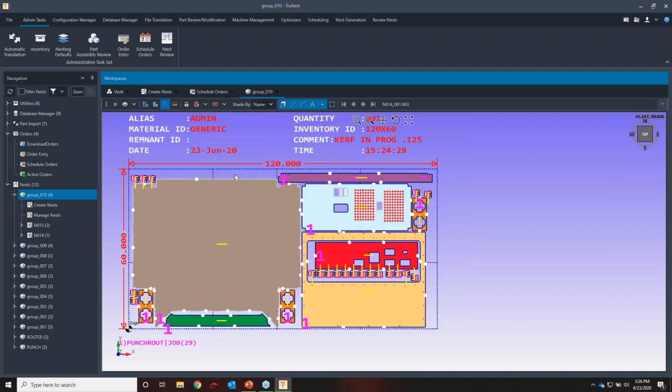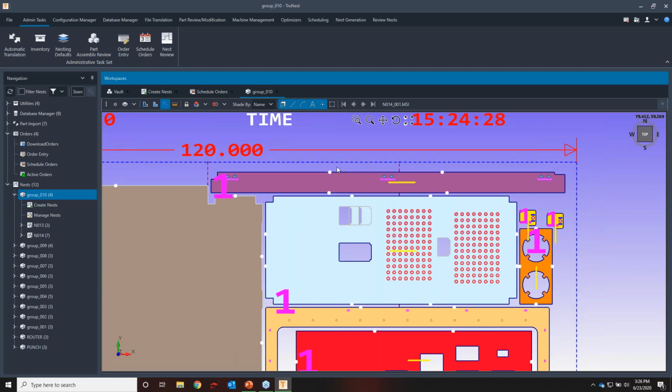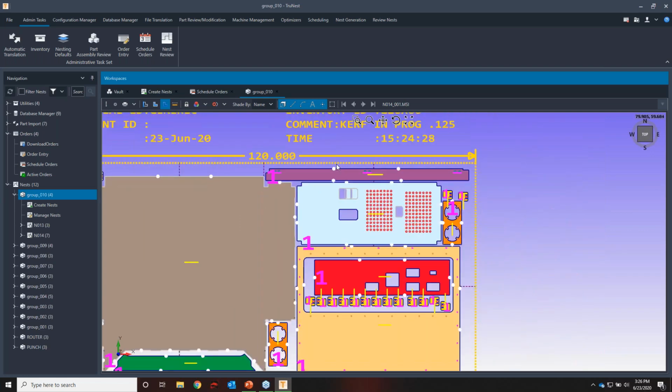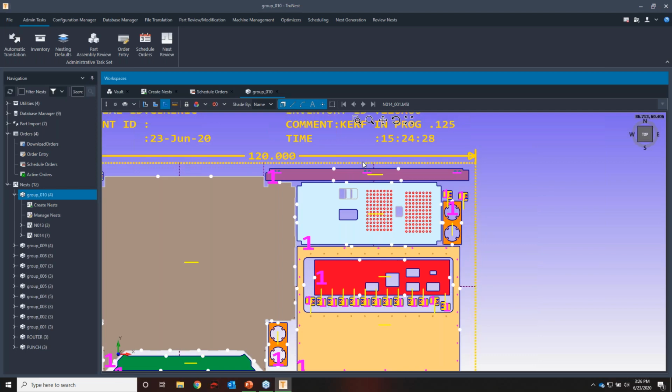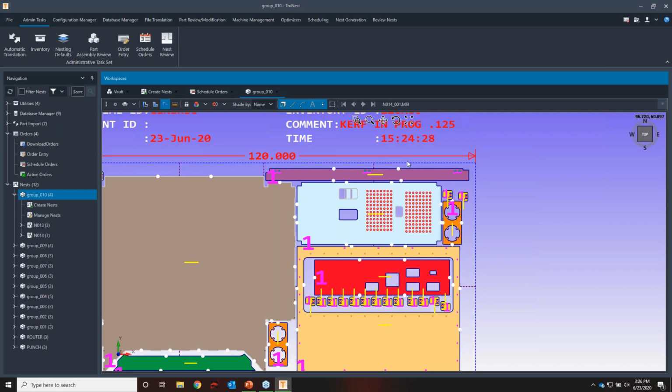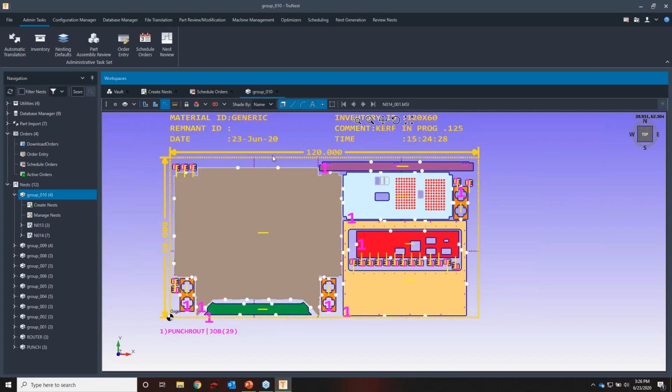But in this case, what we're doing for these tabs is a special process called a skin tab. A skin tab leaves an onion skin thickness. So we process through most of the thickness of the material except for that minor onion skin. And what that does is it never fully removes that particular tab from that part, and it maintains that vacuum pressure better for that particular sheet. So that's something that we do special for the routing process.